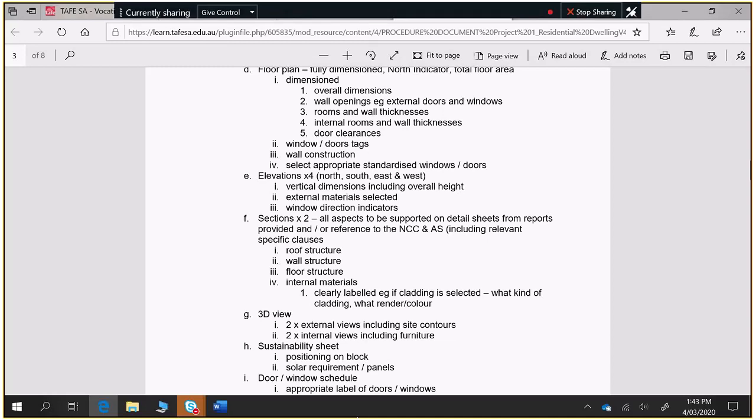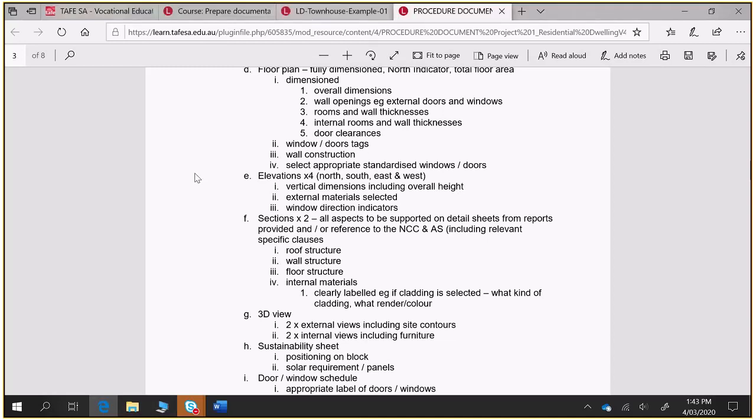And what about the same with the exterior? Do we include the cladding or only still do? So exterior is once again to framing only because it's cladding straight on the framing. If it were brick veneer, well then you do go to the extents of the cladding.